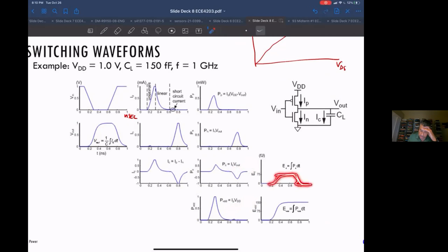we're charging and discharging the capacitor. So there's a certain net energy being charged and discharged in the capacitor, but in the end, you don't have any energy left on the capacitor. But there's a certain energy you've basically pulled from the supply in this cycle. Okay, and that's energy you just used up, you just get it during this output rising transition. And that's the energy used to charge up this capacitor. Well, that's the energy used to go through a full cycle of charge and discharge, because there was no energy coming from the supply during the discharge.